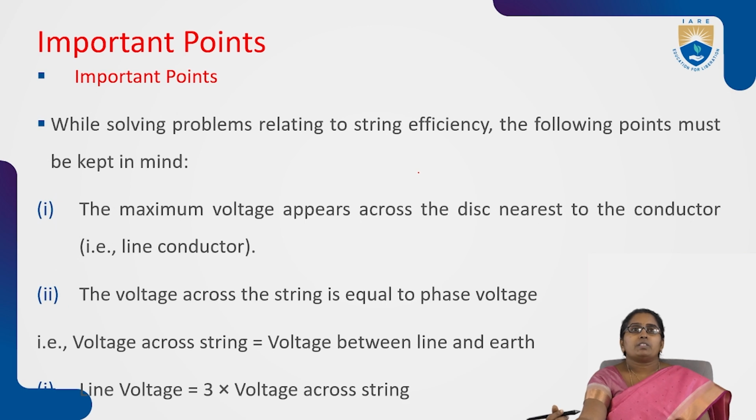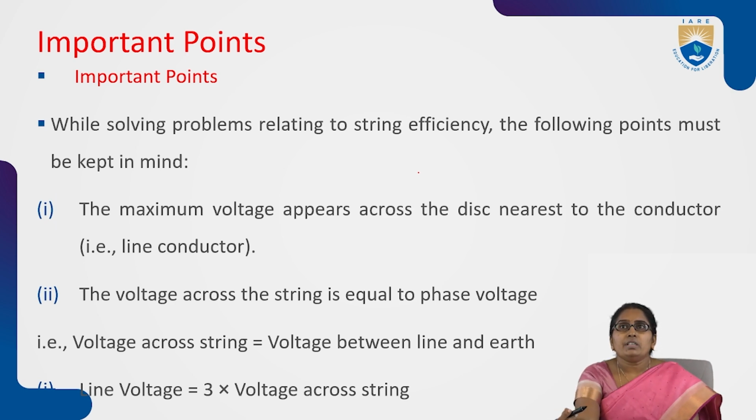Finally, just keep in mind that while solving problems related to string efficiency, first point: the maximum voltage appears across the disk near the conductor. We know this point. The maximum voltage appears across the unit that is near to the conductor, that is the bottom one.